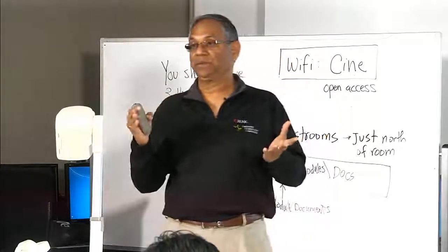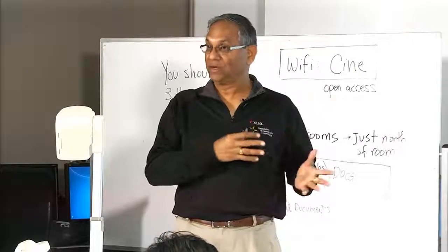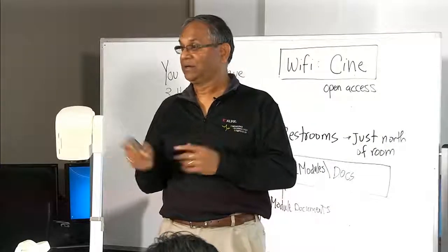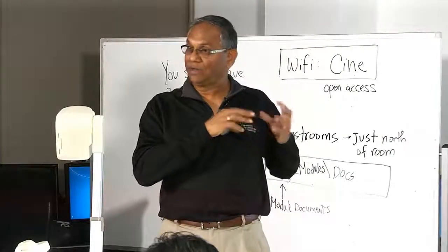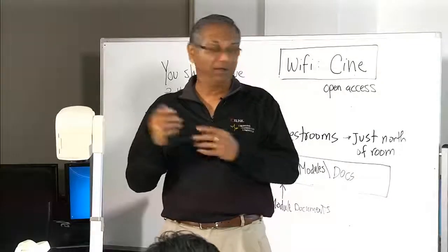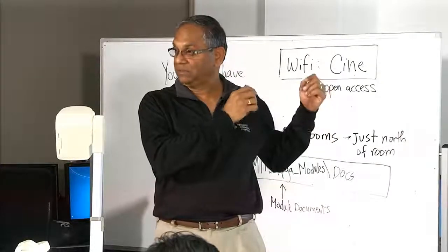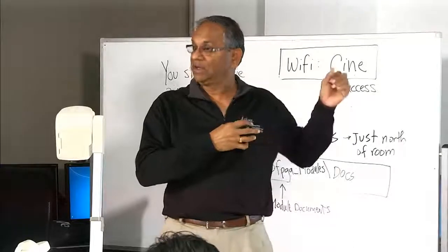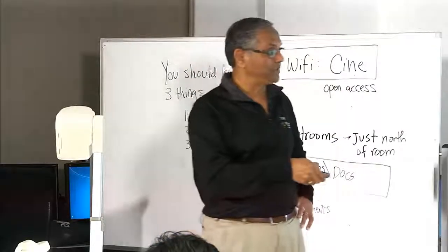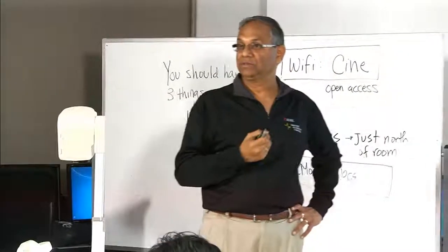Typically what we say is ripple carry adder is slowest compared to carry look-ahead adder. However, if you model a carry look-ahead adder structurally and you model the ripple carry adder behaviorally, it will be faster because it uses this resource which is useful. So, it's important that you write the model correctly.